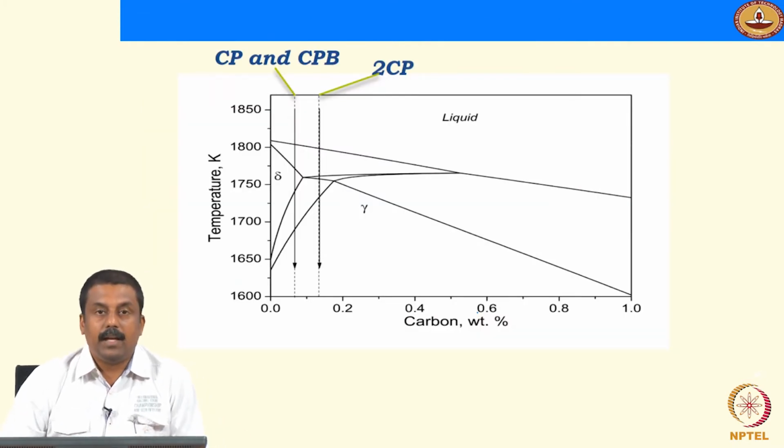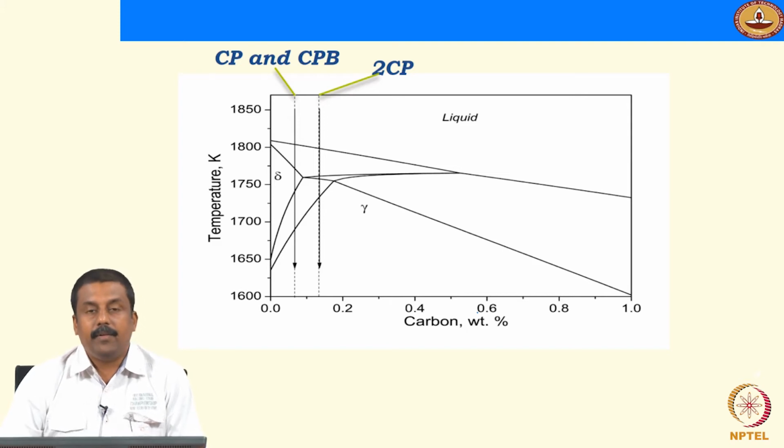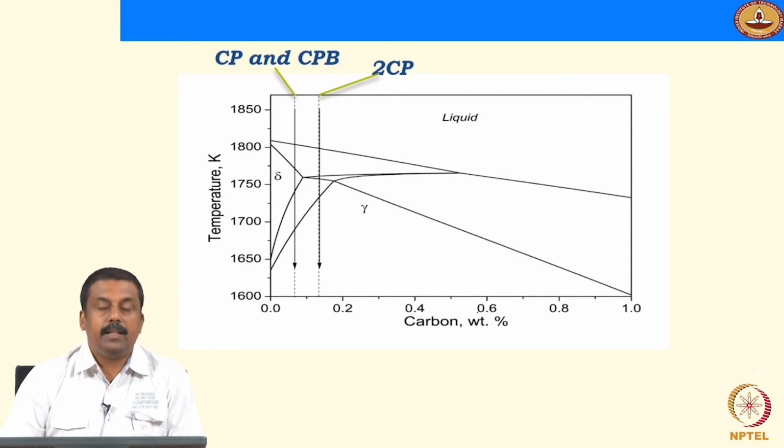The first understanding we have to make when we want to understand the elemental behavior is the solidification mode, how the weld pool solidifies, when you cool a weld pool to room temperature. The mode of solidification is extremely important, because that is going to determine the segregation behavior of the alloying elements, especially the alloying elements which partition towards liquid.